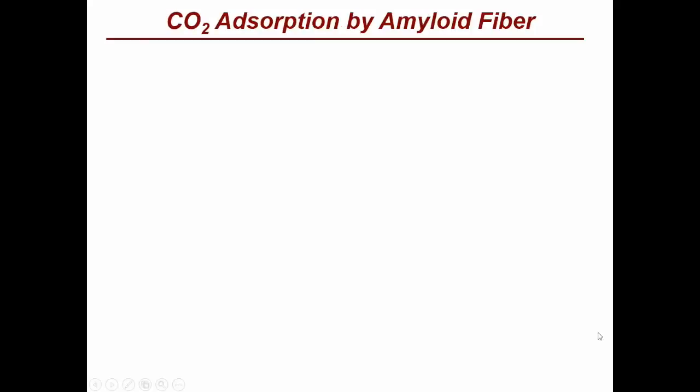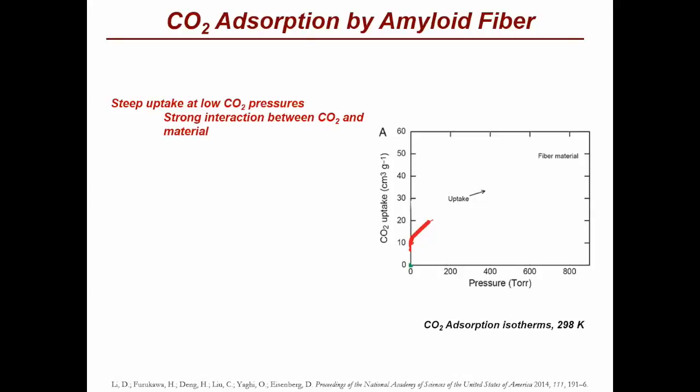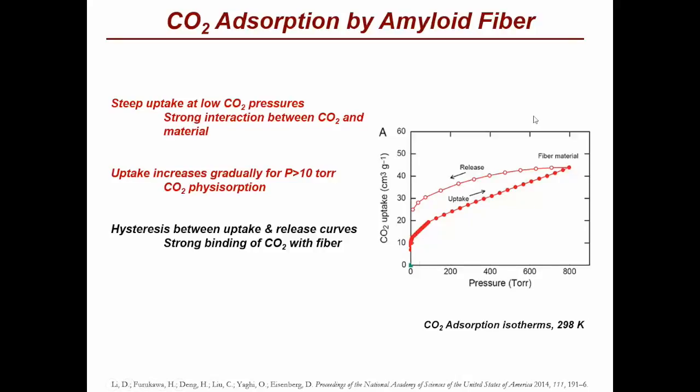The thermodynamic CO2 absorption capacity was measured by CO2 uptake experiment as a function of pressure. At low pressure, the uptake curves were steep, indicating strong interactions of CO2 with the fibers. At high pressures, the uptake was gradual, indicating CO2 physisorption. As the pressure was decreased to release CO2, there was hysteresis present, which again indicates the strong binding of CO2